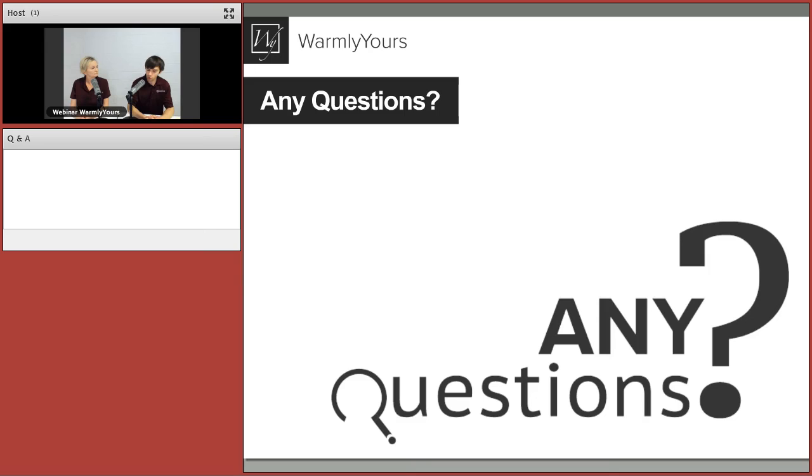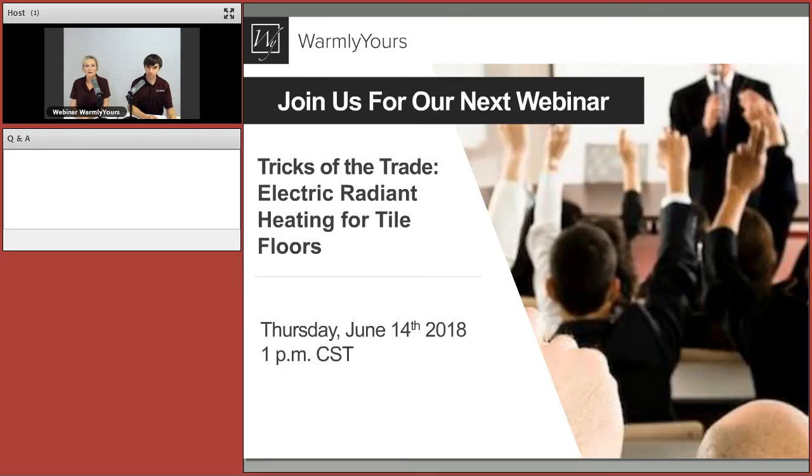And heating cables should never be installed on the combustible surface itself. So if you have wood shingles, that would not be the best combination. That's not the surface you want to lay the heating cable on. And also the heating cable should not be embedded in any insulation material in or under the roofing. In other words, we're not trying to heat your roof here. We're trying to provide those channels itself. Excellent question.